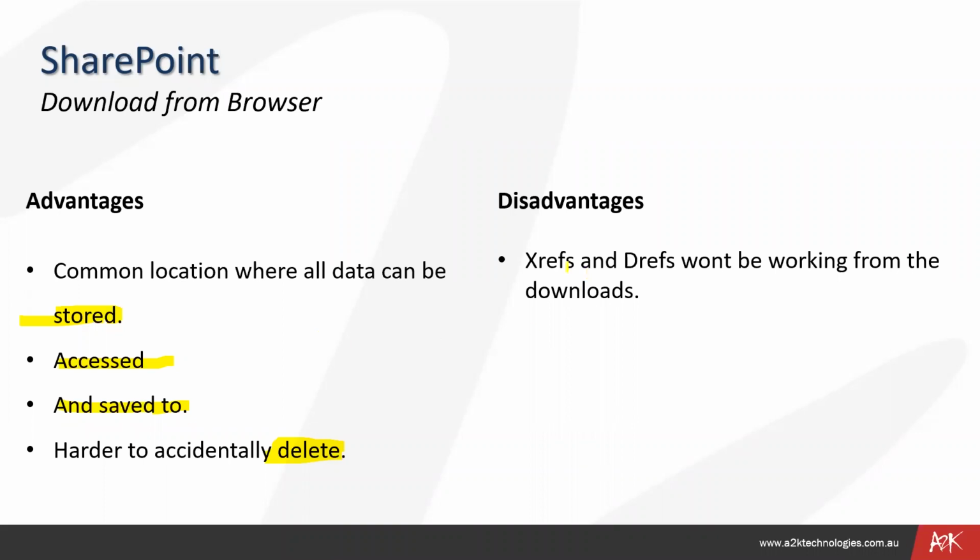The disadvantages are the Xrefs and data shortcuts won't be working. So when you download a drawing, a DWG file, the Xrefs and data shortcuts will be left behind. Okay, so that's not ideal for what we're looking for, I don't think.